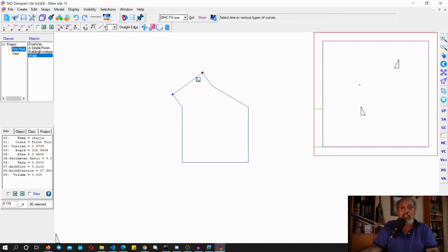The third button is actually to change the edge into various types of curves. Like for example, if I want to have a semicircle over there, I can just say I want a semicircle, but that by itself will not change it, and I will now press that button. It will become a semicircle over there. Now if I press F3 and F4, I can actually get the helpers around that whole shape and do whatever I were doing with the helpers and the architect in the earlier first 2 videos, which were explaining all that quite well. So there you have it.